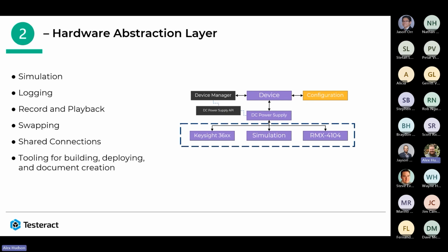But all of that is our object-oriented based stack, and then we build a little bit of a wrapper on top of it, which is an API, and we have tooling for this that automatically gets generated off of our device type. And so we can automatically include logging and reference management and all sorts of stuff within that API really easily, and that's all done for us. Us as devs never have to think about the API. It's all made by a tool because every device in our HAL is built the same way because we use a framework. So using a good framework allows us to make some assumptions, which allows us to build tooling, which is very nice. So that's our HAL.